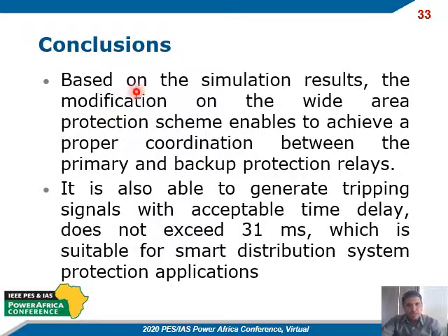Based on the simulation results, the modification to the wide area protection scheme is able to achieve proper coordination between primary and backup protection, and it is able to generate tripping signals with an acceptable time delay not exceeding 31 milliseconds, which is suitable for smart distribution system protection applications.